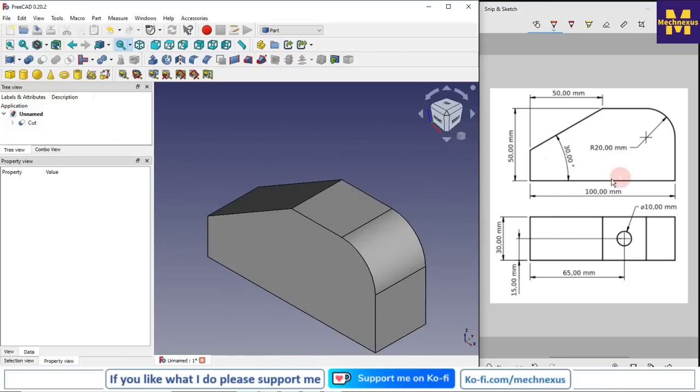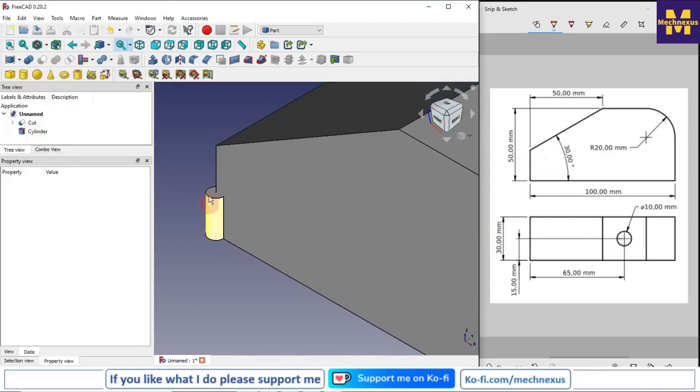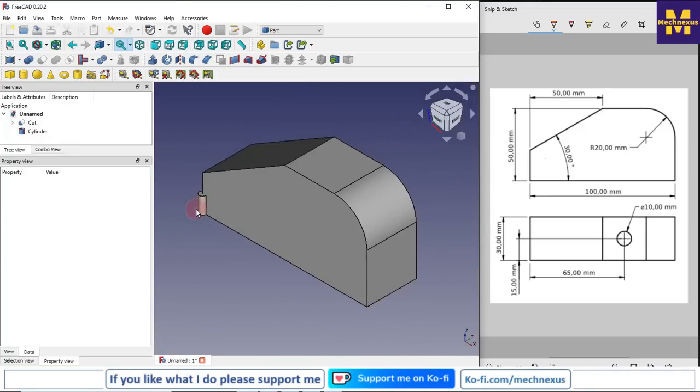Now we will make a hole on the part of diameter 10 mm. So we will simply insert a cylinder. So you can see that it has been inserted here, and now we will change its position and then we perform the boolean operation.